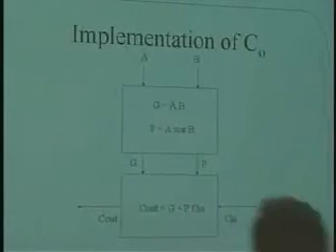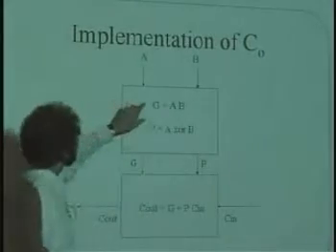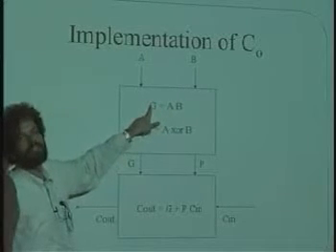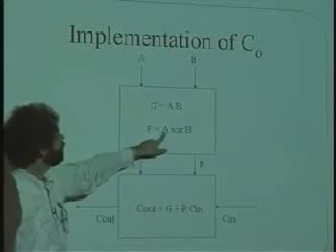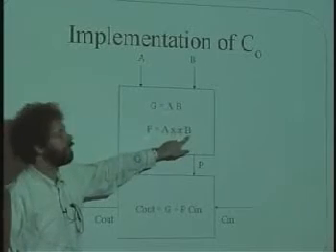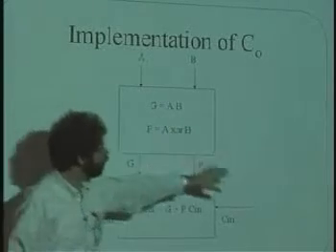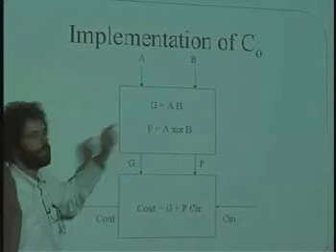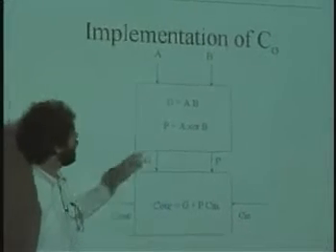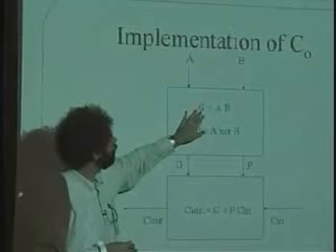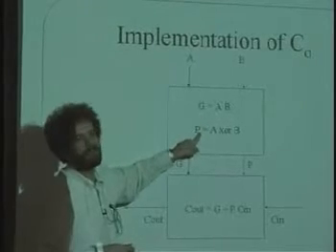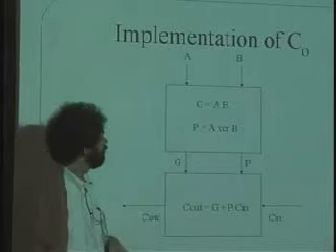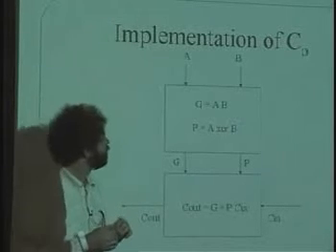Okay? We have a preprocessor to generate G. Generate. If A is true and B is true, then generate the carry. If A is true XOR B, and again, this computation takes place before C sub in comes in. Pre-processing that's done, then we're going to propagate the carry. Okay? And we set these things up so that if generate is true, propagate is false. Because when we generate, we don't really propagate, we just generate. We're sort of blind.